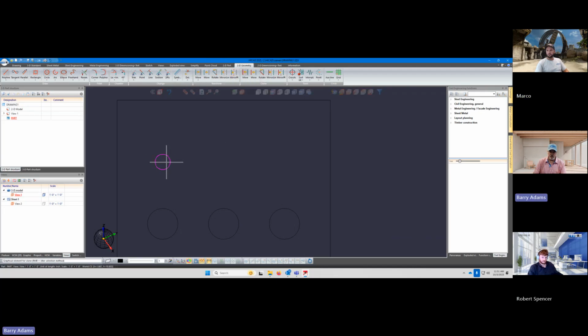Okay, I'm not getting this thing to select it, right? Yeah, just click once to select it. Now displacement vector. So where's your start point? Again, center point would be a good option here. I guess we want it right above this one, right? Yeah, which is 1 inch over. So as long as you select the displacement point and drag it over 1 inch by either spacebar input or just the cursor, it should be right. I'll go with that and drag it over.